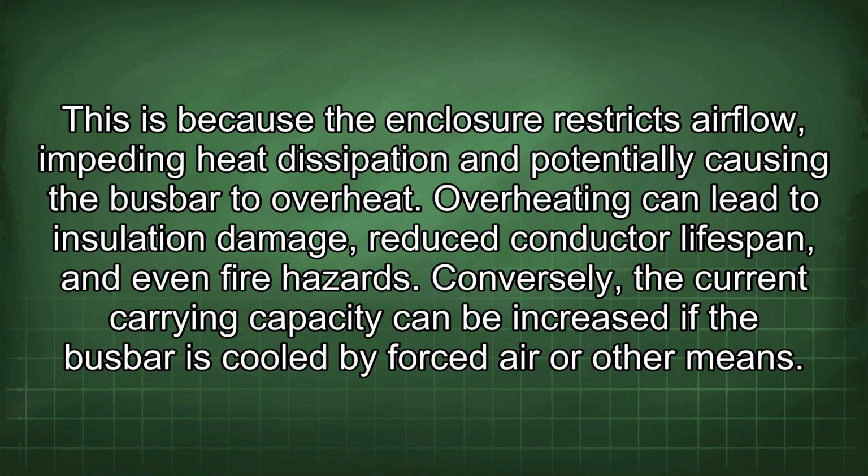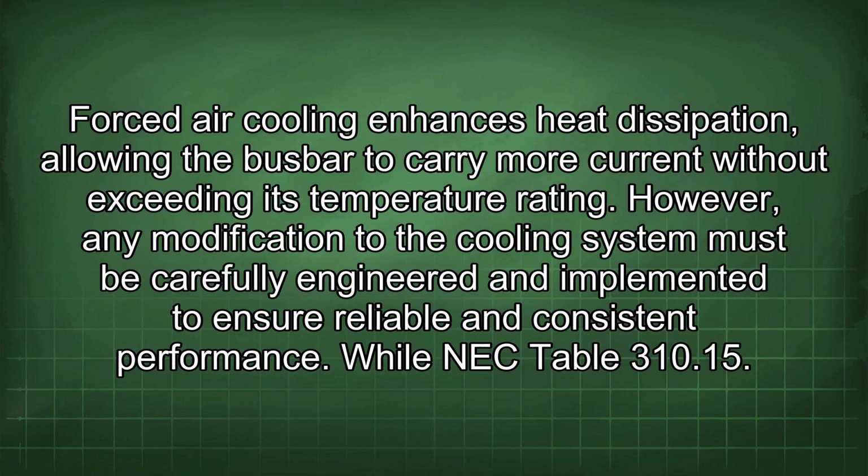Conversely, the current carrying capacity can be increased if the busbar is cooled by forced air or other means. Forced air cooling enhances heat dissipation, allowing the busbar to carry more current without exceeding its temperature rating. However, any modification to the cooling system must be carefully engineered and implemented to ensure reliable and consistent performance.